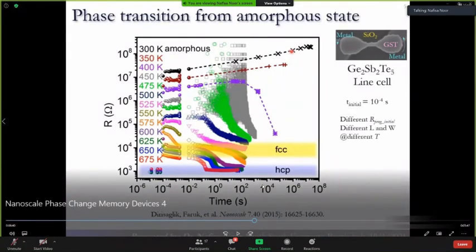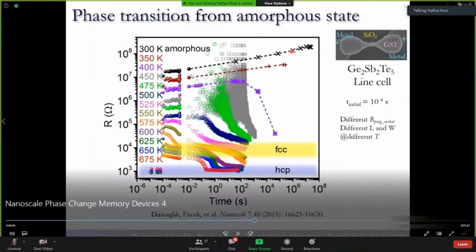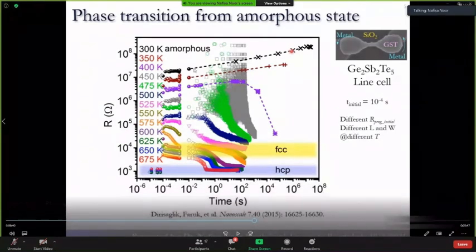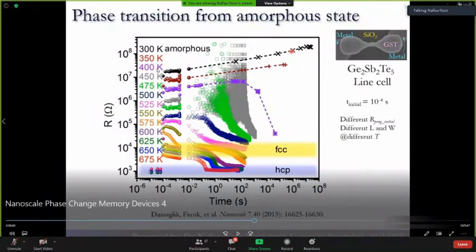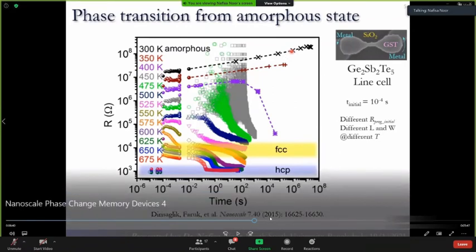Now, you may ask then, how can we use this in the applications of automotive and maybe in the industrial applications where high temperatures are involved. So the idea is that up to 120 degrees Celsius, the PCM can tolerate the temperature, this transition. It has a thermal stability. So 120 degrees Celsius is marked as the higher bar for a safe temperature zone. But above that, you would see acceleration of the data loss. So that is the explanation of this slide 5. Is there any other question on this slide?